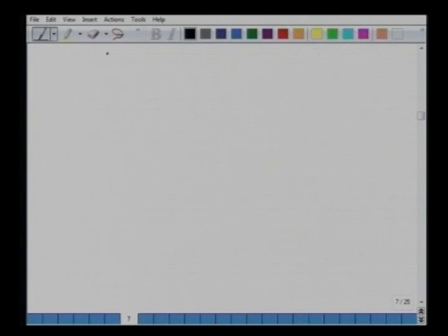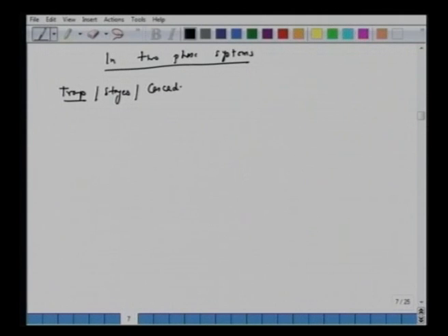So whenever you have the equilibrium stage-wise approach, one very common approach is that you identify two coordinates which are in equilibrium, given by the tie line, and two coordinates which are on operating lines, not in equilibrium, so there is a finite mass transfer. Okay, so we would like to just sum up what we said here about this species balance. In general, if you have a two-phase system with the tray-wise approach, or stages, or you have cascades, then first we are talking of two phases with two different concentrations or mole fractions.